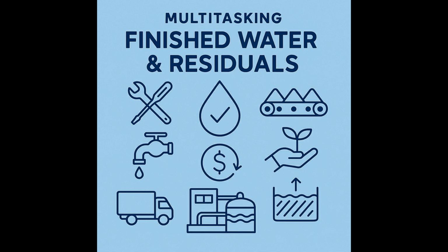Pros and cons of the BFP? Advantages include a moderate capital cost compared to centrifuges. It's a very proven and reliable technology, and it produces a reasonably dry cake, again, often 15 to 25% solids. A key thing operators often like is that it's visual. You can actually see the sludge being dewatered and make adjustments on the fly.